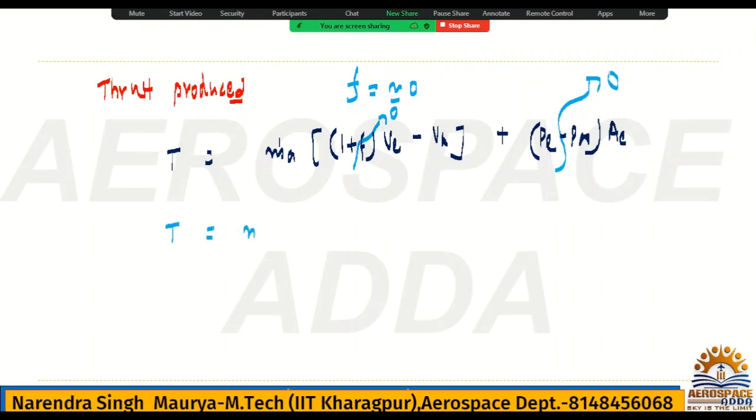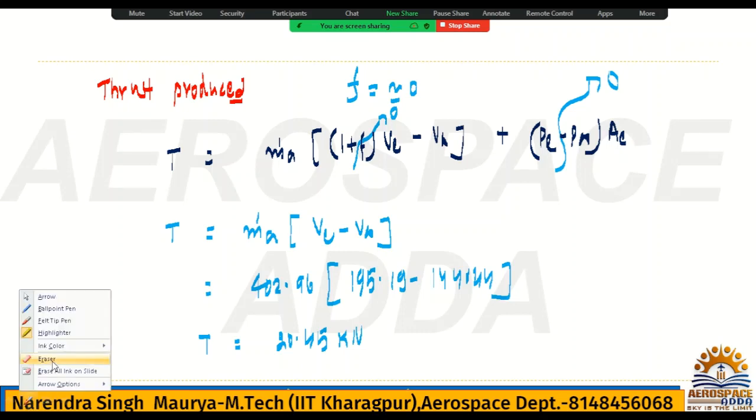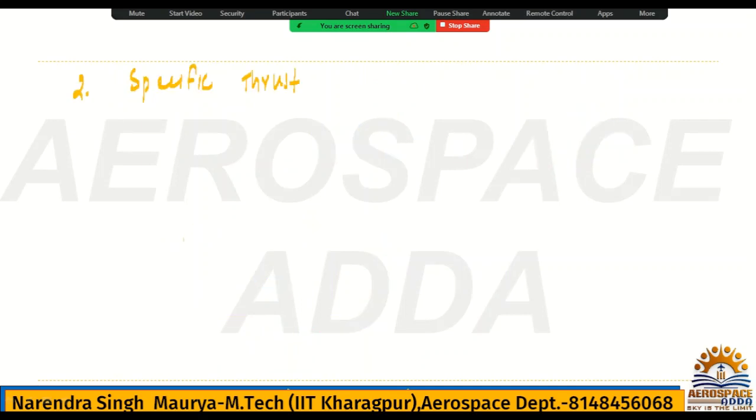So what will be thrust? M dot A into Ve minus V infinity. Just now you have calculated m dot A 402.96. Ve you had calculated 195.19 meter per second, and V infinity was 144.44 meter per second. Yes or no? So if you solve this, you will get 20.4 kilonewton approximately.